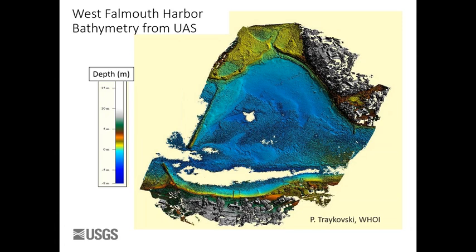How rapidly is it taking pictures? It ends up being 1 to 2 seconds. It depends on how fast you're flying and how high you're flying. And there's software that allows you to plan all that. So you say, well, I want a pixel to be a centimeter on the ground, so that means you have to be this high, and that means if you want 60% overlap, that you have to go this far, and if you're going to fly at 10 meters a second, the software will help you figure all that out.